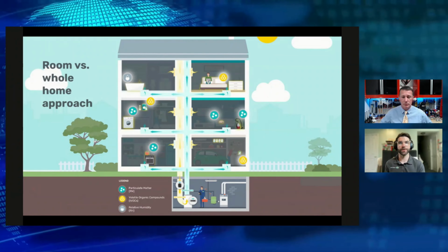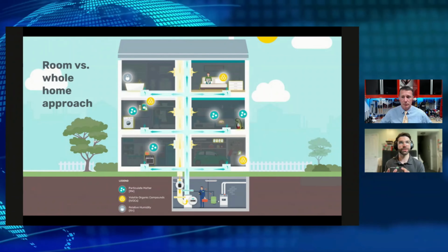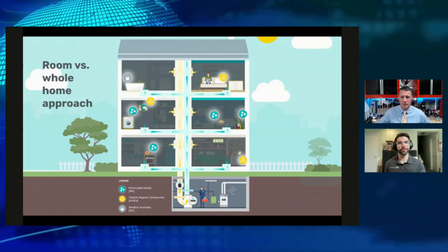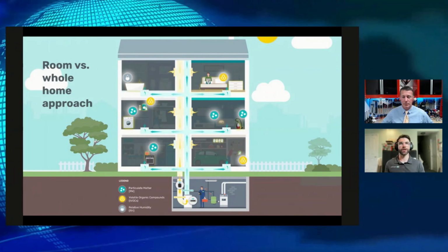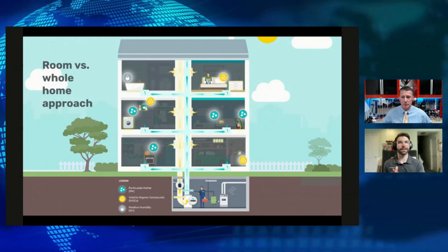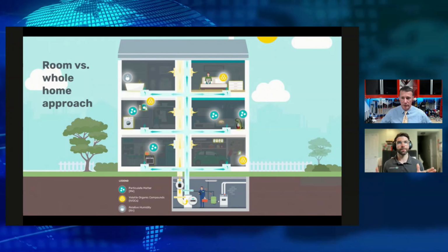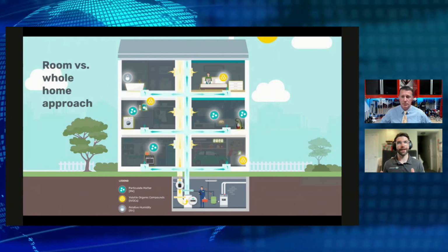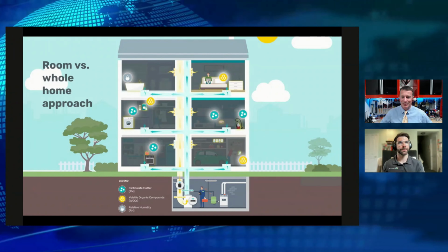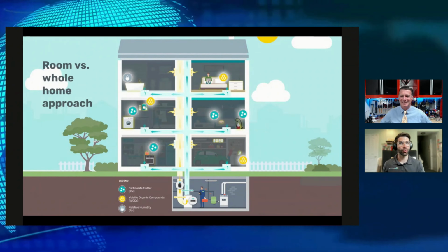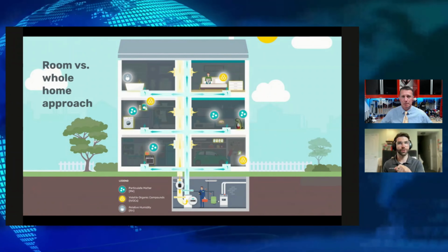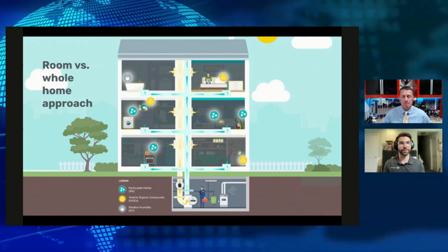The next reason why this is valuable is it's bolted into the duct, and it's actually looking through the airflow of the system. When the system's turned on, it doesn't require a fan or a pump. So it is solid state. It can last for a lot longer than a room monitor because there's no moving parts. And one of the issues we see with the room ones is that they can be unplugged. They're just sitting on the tabletop. And so, they're going to end up in a drawer. Well, the good thing is the homeowner's not going to go into the utility room, unscrew the monitor, pull it out of the duct, and put it in the drawer.